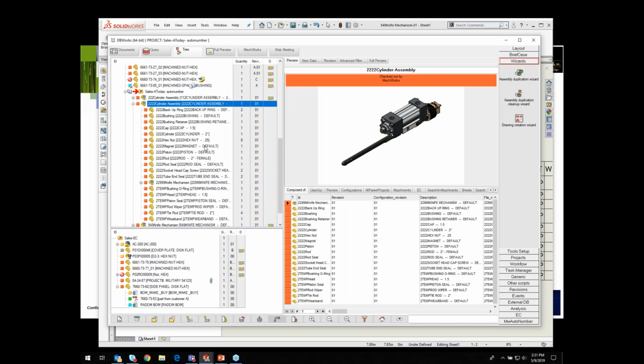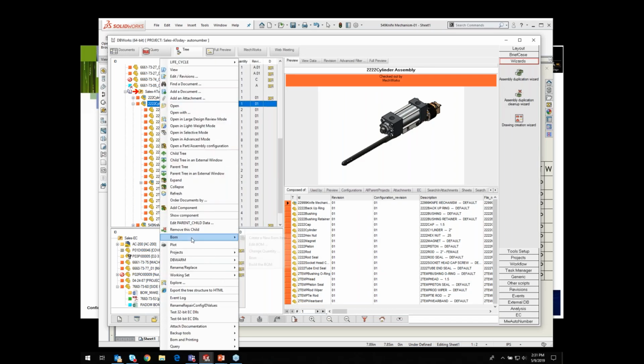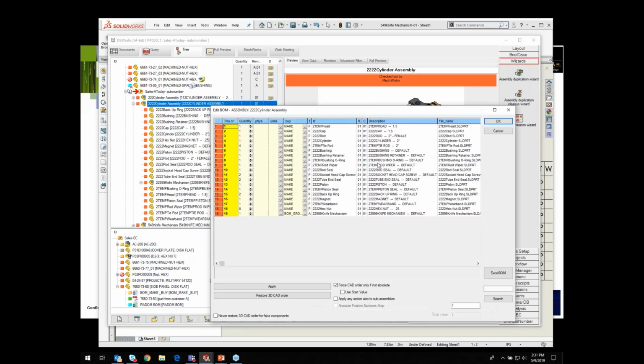So what you could do is you just go to the top bill of material, you edit it, you find that knife, and in here you would go no expand, which is saying I still want this knife mechanism, this sub-assembly on here, but I don't want all the parts to go with it, because really I'm going to buy, as far as this bill of material is concerned, in this assembly, I'm kind of putting that knife in as a completed element. Hit OK.